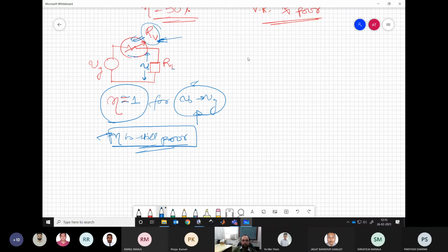Typically we can have a BJT operating in the linear zone or the active zone, where this VCE voltage is dependent on how much IB you are injecting. So there is a linearity between the IB injected and VCE drop across the device. This could be a good option for having an automated system for the variable resistor.